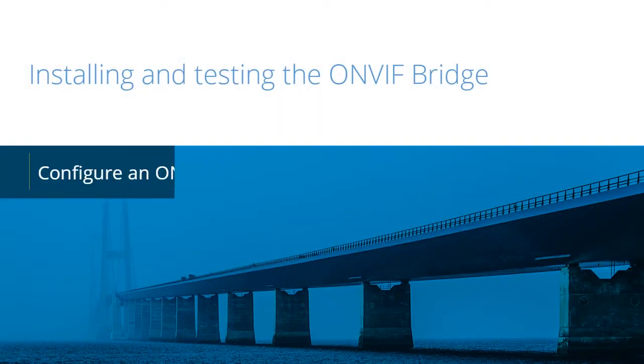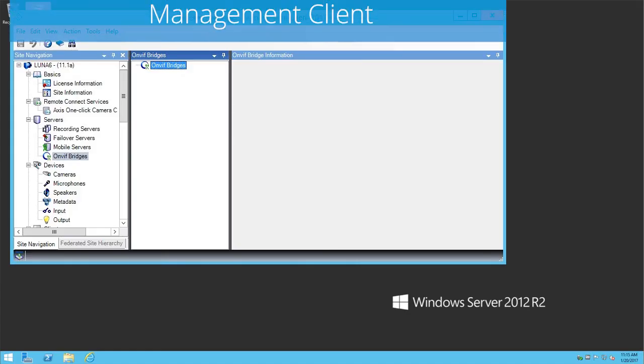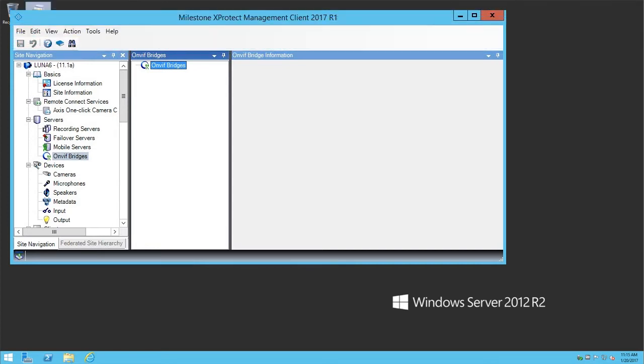The Milestone ONVIF Bridge helps organizations share video with external agencies. In this video tutorial, you will learn how to configure an ONVIF bridge in the management client. We've created an ONVIF server that is pointing to the XProtect management server on this machine.